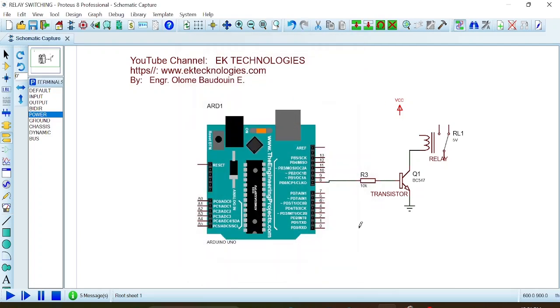Okay. So you can now connect these to the relay, then a diode. The diode here is connected at this terminal of the relay. This is what we call a freewheel diode. This freewheel diode will permit to counteract the back EMF that is caused when the relay switches, so that it doesn't affect your control circuit. It doesn't affect the microcontroller as well due to back EMF generated.